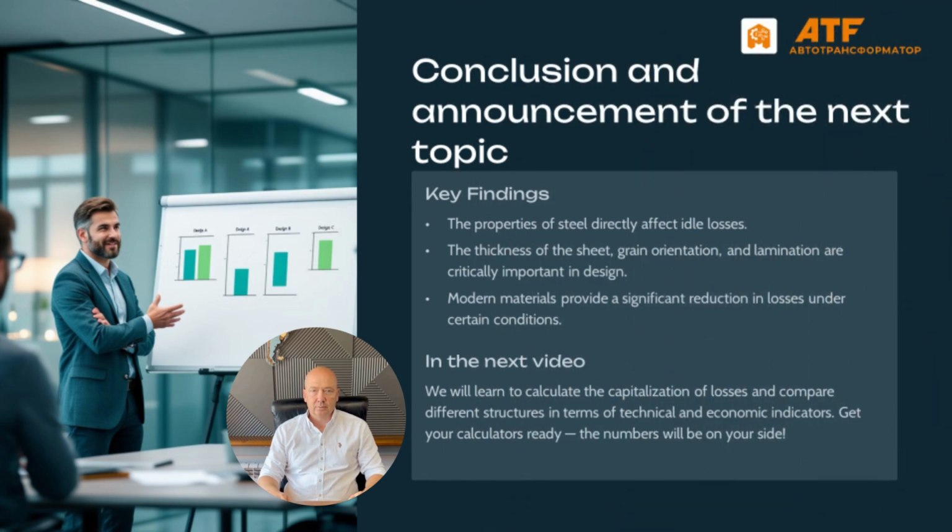Today you've learned how steel properties affect no-load losses in a transformer, why sheet thickness, grain orientation, and lamination are key design parameters, when it makes sense to use advanced materials, and when it doesn't. In the next video, we'll learn how to calculate loss capitalization, how engineers compare designs and make economically justified decisions.